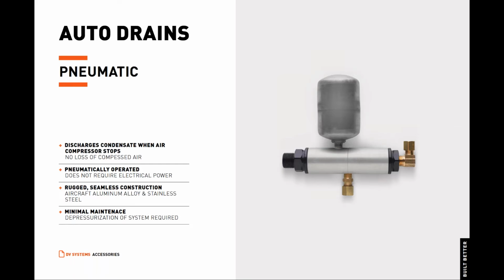The pneumatic auto drain features anodized aircraft aluminum alloy construction with a stainless steel accumulator or reservoir, stainless steel ball, piston rod, springs, strainer, retainer, and screen, along with Teflon and Viton seals.